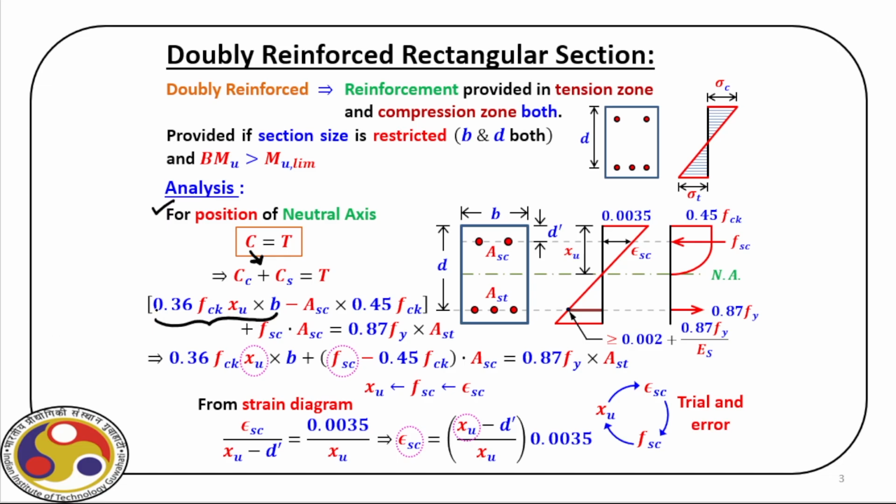Now, when you talk about this part, it actually considers the section, say we have neutral axis here. Then above the neutral axis, the complete section under compression, and that concrete we consider to evaluate this force. Obviously, we have considered one area of ASC and that we subtract.